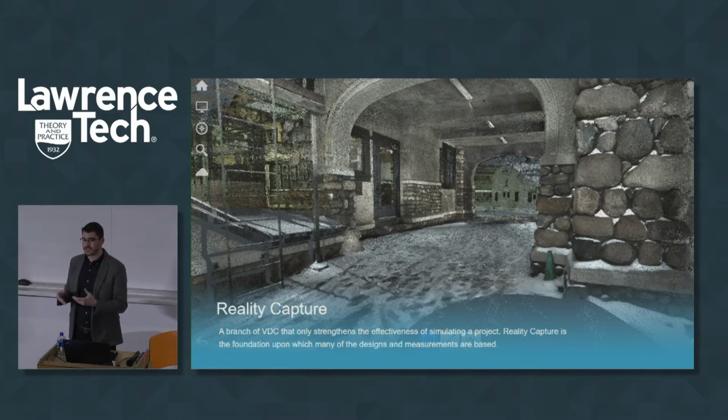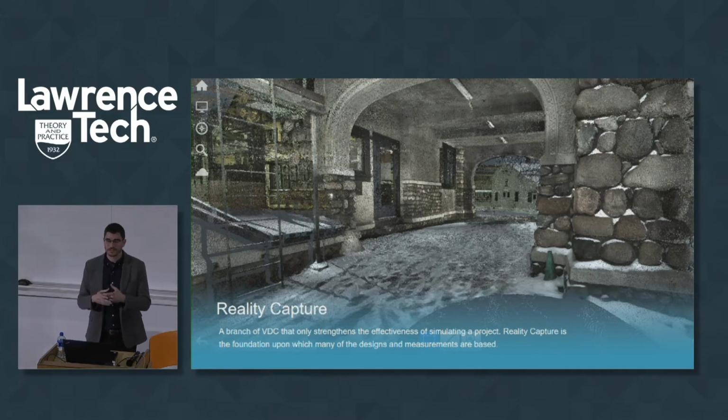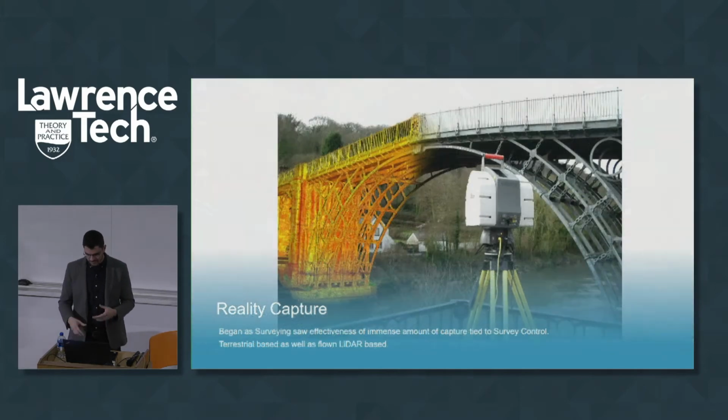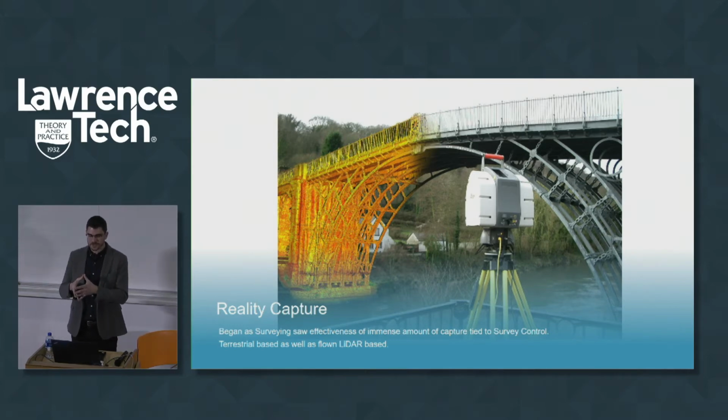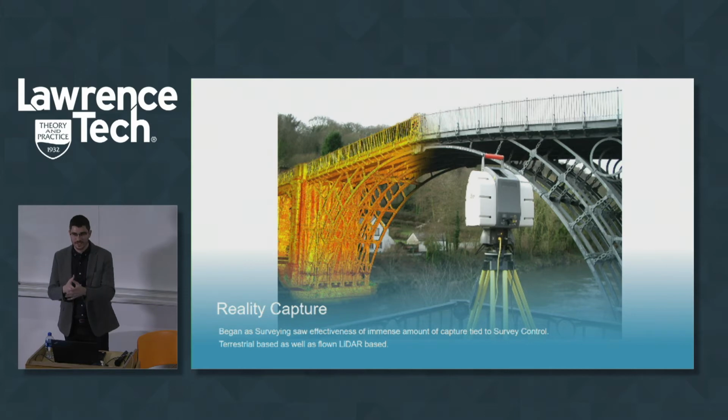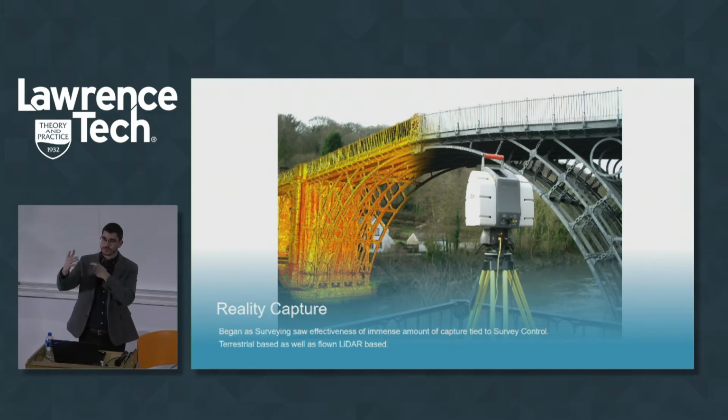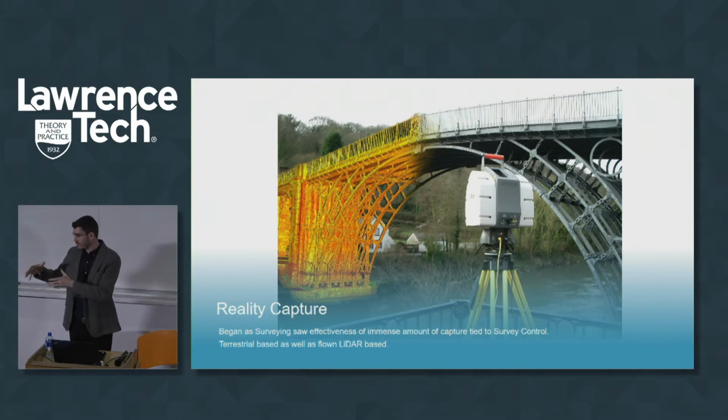So some of this data is so detailed that it's almost getting to sub-millimeter accuracy, where you can begin to set up a scanner within this room and capture the whole room down to the millimeter for each individual piece that's involved with this. So it really began with the surveying industry, I would say, where a lot of these guys, they call them gizmologists, were kind of tinkering with these lasers, and they had this laser that could shoot out at a building corner and bounce back, and the time of return for that laser getting back to the machine would then equate to a measurement. So based on how fast that light is moving and how long it took, will give you a measurement. And so from wherever that scanner is set up, it's going to tell you what that dimension is.